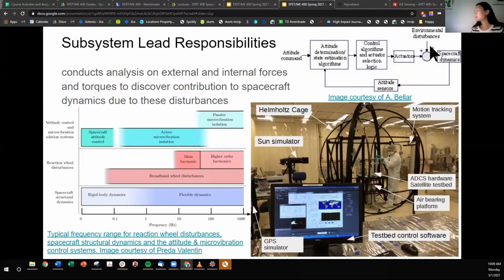So these environmental disturbances, they're not known, they are measured or estimated to a degree. So if they're not known and you have to measure them, then your spacecraft needs to react, which means it measures and then acts post-measurement. If you do know your environmental disturbances, then you can proactively reject those disturbances. So you are adding control before you experience the disturbance itself.